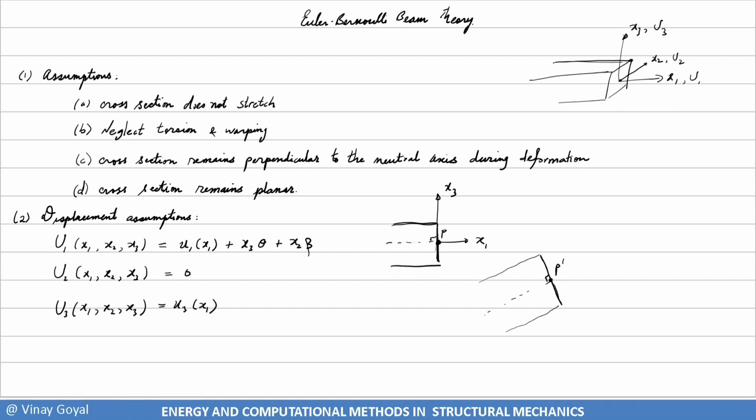So as a consequence, you can see that for very thin, very long structures, when you bend them, the cross-sectional area will stay somewhat perpendicular to the neutral axis. So that's a very good assumption that can be made. So we can see here then that when x3 is 0, we're going to assume that u1 right here is 0, because we're assuming that any rotation about the axis x2 means there's no deflection u1. But we can see here that when x3 is 0, the deflection is u1, and that deflection represents this distance here.